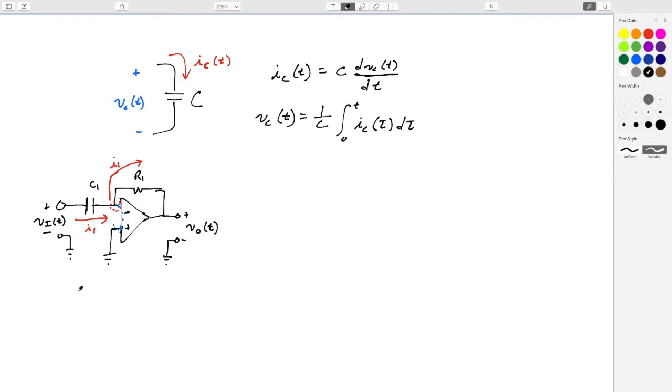So for our expression for I1 as a function of time, because we're with capacitors now in the time domain, we need to generate our component equation. We can take the one up here and use it. We just need to map it over to the voltage we're seeing here. The voltage across the capacitor in circuit-specific terms is going to be Vi minus 0 volts.